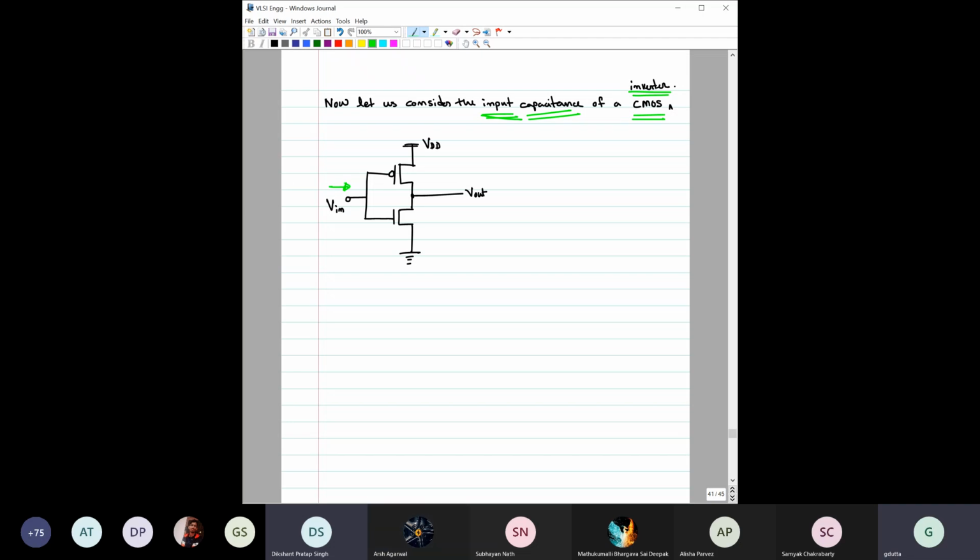So, Arsh, initially you mentioned that it might be possible that both the transistors are in triode. Is it possible for a CMOS inverter? No, sir, I don't think so. I didn't do a detailed analysis, I just threw it in the air. I just wanted to consider a single case. It's not possible, right? Because we have seen the regions of operation. It's not possible that both transistors are in triode for a CMOS inverter. So consider one in saturation, one in cutoff, then it is possible.